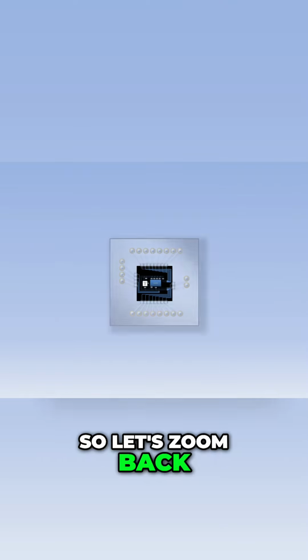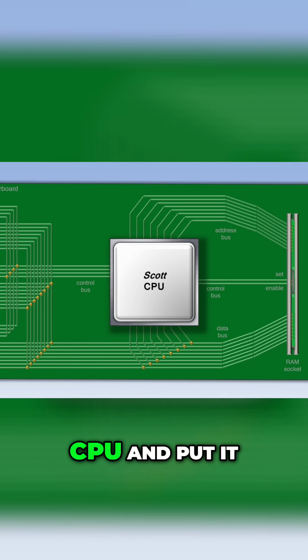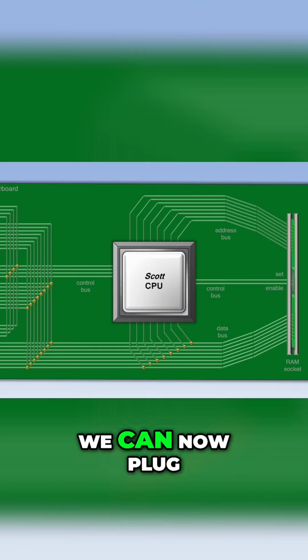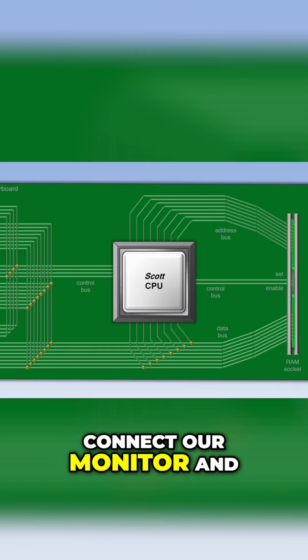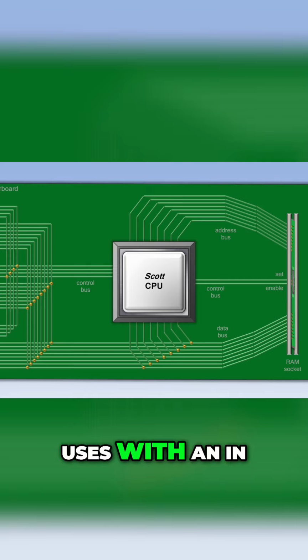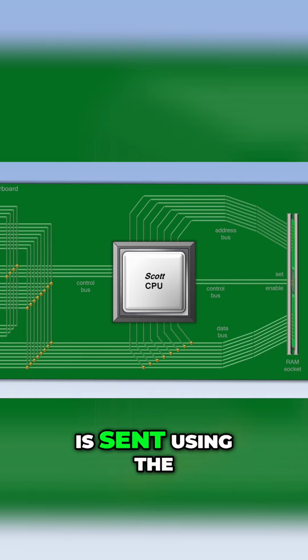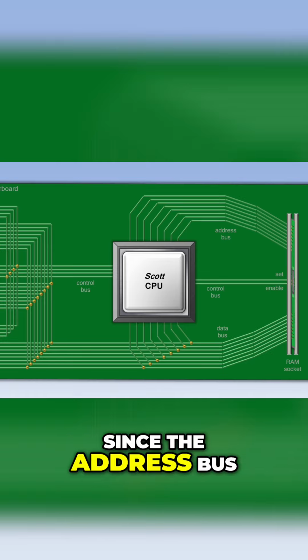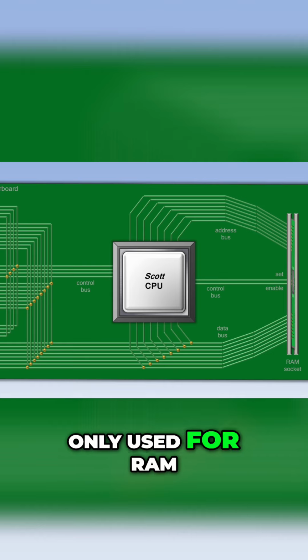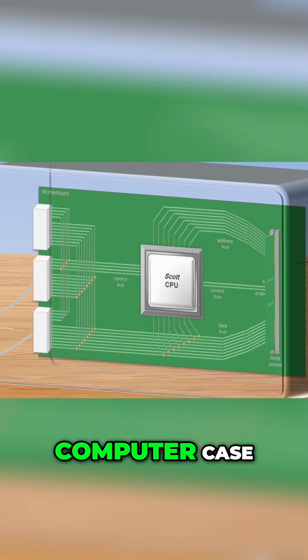So let's zoom back out to see the rest of the chip, and we'll put the cover back on the CPU and put it back in the motherboard. Using the ports on the left, we can now plug in the cables that connect our monitor and our keyboard. Each of these ports has an address, and that port address is what the CPU uses with an in or an out instruction. That port address, by the way, is sent using the data bus, since the address bus in this computer is only used for RAM. So we'll zoom out to see how the motherboard fits inside the computer case.